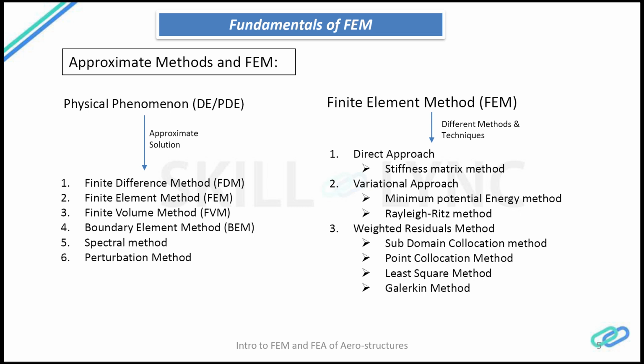So in your finite element course in engineering, you might have come across two types of refinements, which are H refinement and P refinement. H stands for increasing the number of elements, and P stands for polynomial, which is if you are using higher order elements. In finite element terminology, you use a simple rod element which has two ends, two nodes, and there are some higher order elements which might have three nodes for the same rod element.